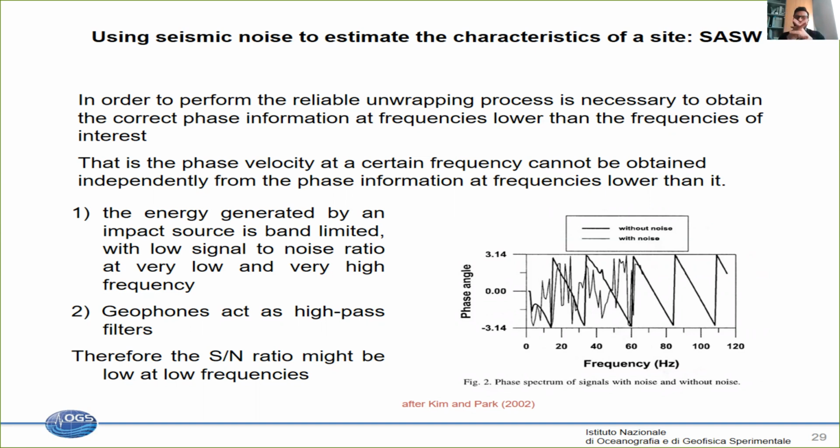I start even a little bit before, and also distorting the frequency. So if my filtering is very strong, what can happen? That at a certain point, the signal can become smaller than the internal noise of the sensor, like we have seen last time. And if this is happening, I have no information anymore on the real signal that I excited.